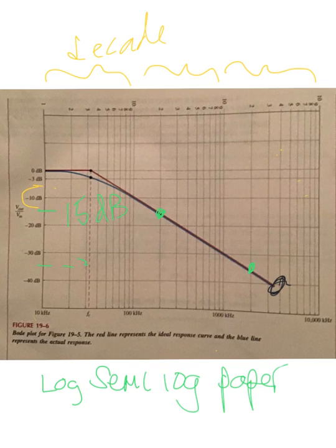And I think we're at about minus 35 dB here. What's the difference between 15 and 35? Minus 20 dB per change of 10 in frequency. Now that is 200 kilohertz, and this is 2 megahertz. It's the same as 100K and a megahertz. It's the same, okay?